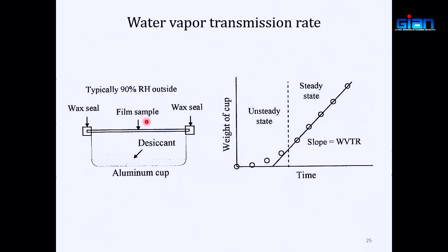Well, you have learned the water activity concept, right? So in the water activity concept, what do we have? Equilibrium RH by 100. Yeah, so you will get 100% relative humidity. So this is the gravimetric method for measuring the water vapor transmission, right? You are measuring basically the weight change for this cup. With a desiccant, you have weight gain, but if you have water, then you will have weight loss. That's very easy to measure using a balance.